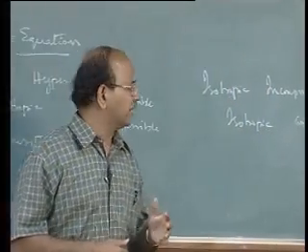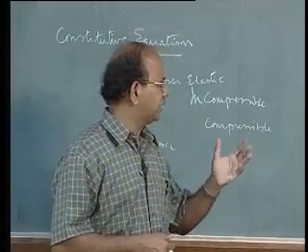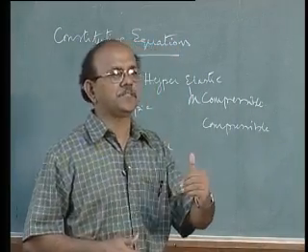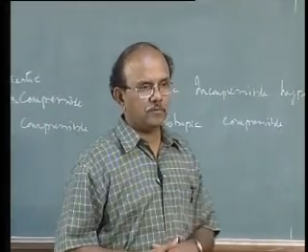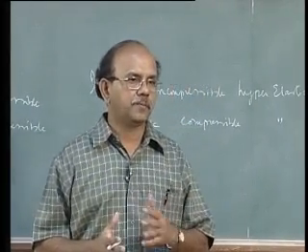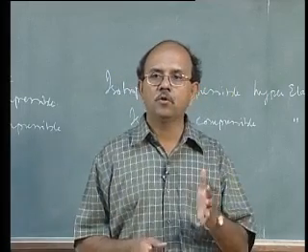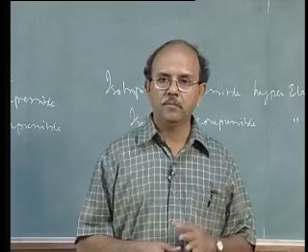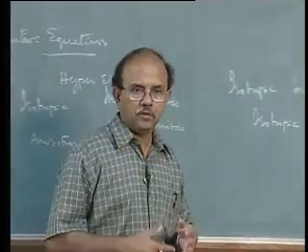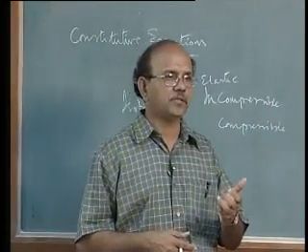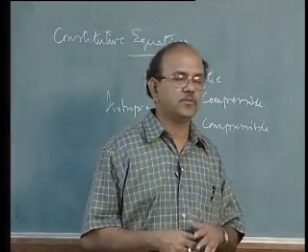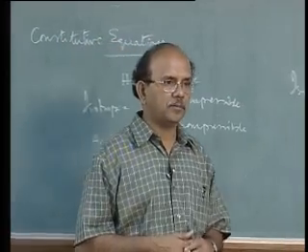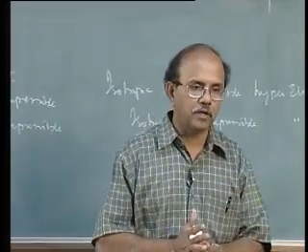And of course, you can also classify another category of materials called isotropic nearly incompressible materials. But usually you do not put down a separate constitutive equation for it, but you can also say that there are some materials which are nearly incompressible. But many times, because of the finite element formulations, we treat incompressible materials to be nearly incompressible and so on. That we will discuss when we come to the finite element part after 2 classes.